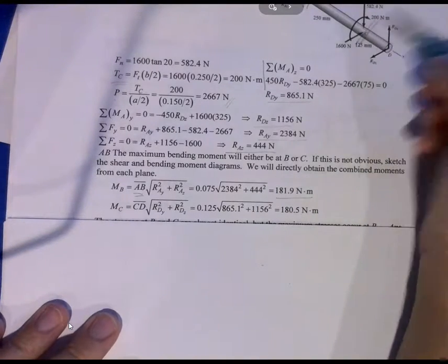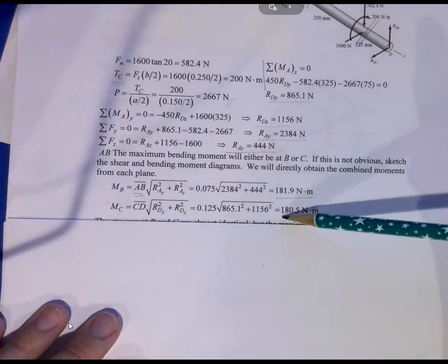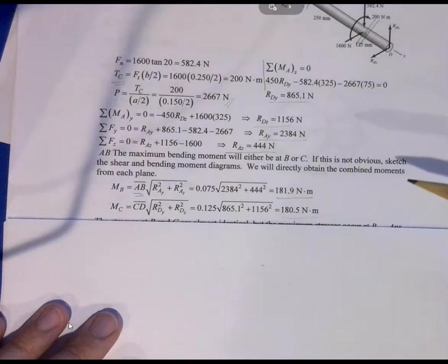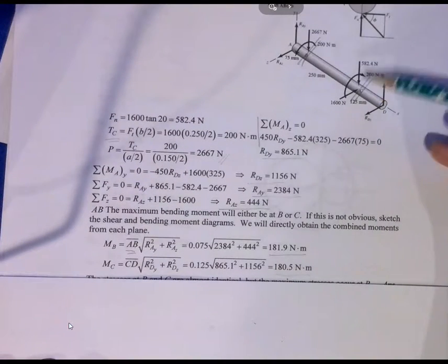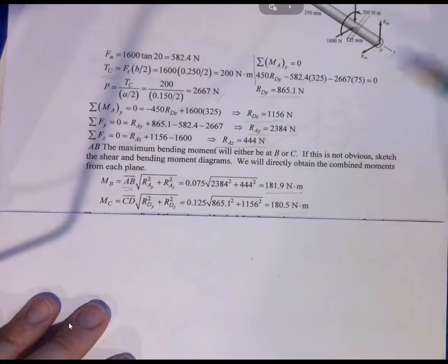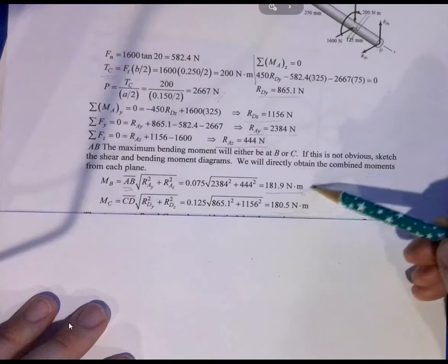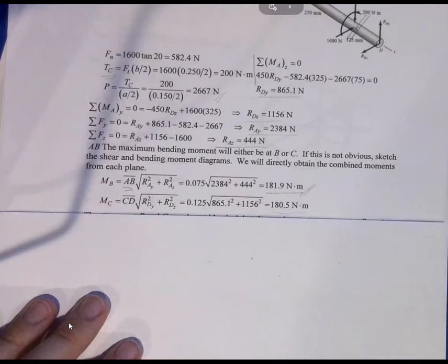If we cut the bar at C, where I only have to look toward D, I can do the same process, and I can find that they are nearly identical, which means that the slope of my shear force between B and C, or the value of my shear force, is nearly 0 because the slope of my moment diagram is nearly 0, but the bending moment at B is slightly higher. And so now we continue using the bending moment at B to determine the bending stress.